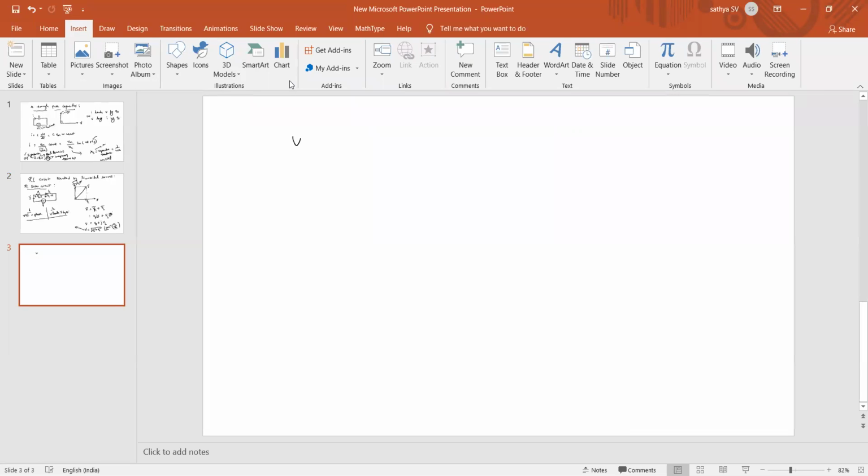So what we have now is V equal to VR plus VL. V is nothing but I into Z, that is, total current into total impedance of the circuit. And VR is I into R, at 0 degrees, plus VL, which is I into XL at 90 degrees. So that equals I times (R plus j XL), that is I into Z. So I will get cancelled.